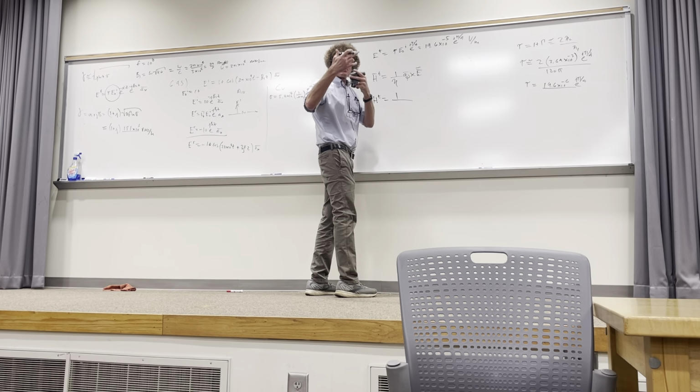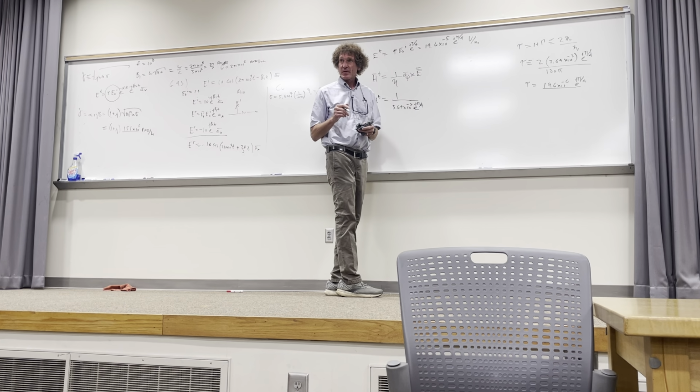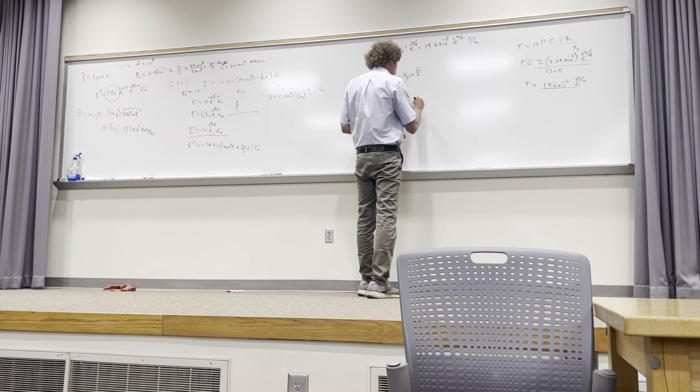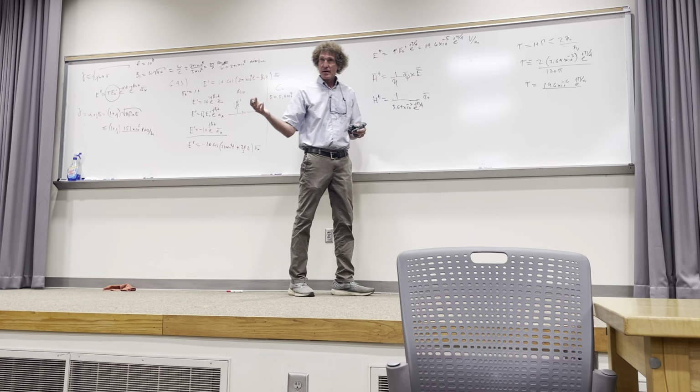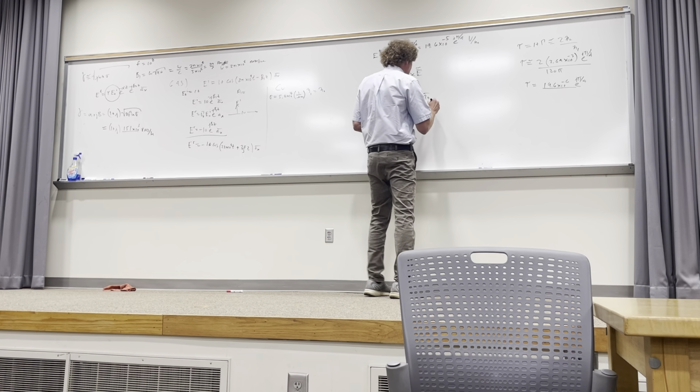Eta is some super small number, which is what? 3.69 times 10 to the minus 3, but it's e to the what? J pi over 4. You got to add the angle there. With me? Then it's going to be unit vector in the direction of propagation is AZ, correct? I'm doing it in the phasor domain first, and then it's crossed into the E field.